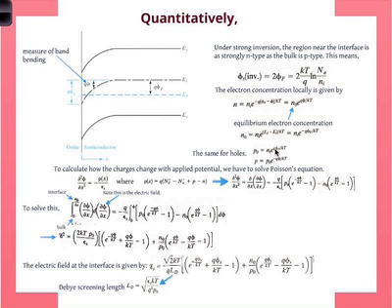Now we need to relate the concentrations of these holes to the applied voltage. Remember, our goal here is to say, if I apply this much voltage, how many electrons come here, so I can calculate what the current is this way. That's basically the goal, and we are just doing the first part of it. So we need to relate the electron or hole concentrations to the applied voltage, which we have to some extent because the bending depends upon the applied voltage. So the logical progression here is pretty straightforward.